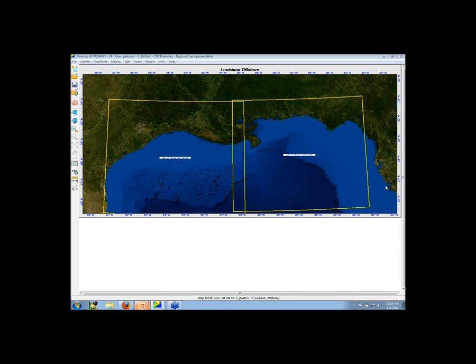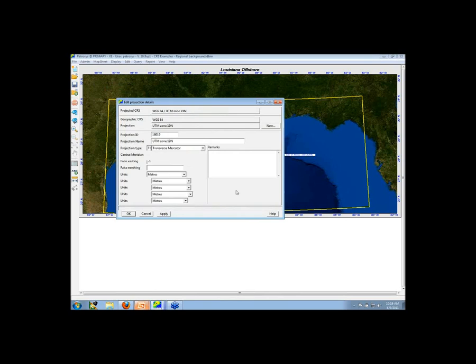So I've got a map here. I'm projecting an image. This is actually the WMS image in WGS 84, and Petrosys is reading that information in the background and is able to reproject it into a new projected CRS. I'm projecting everything here in a more regional type of CRS called the Louisiana Offshore. It's pretty easily controlled in Petrosys. The first thing you do whenever you create a map is define your area of interest as well as the CRS, and we call those things map sheets, and I can just pop open some of the details here. These map sheets, like I said, have the projection system defined, so we're looking at things in a NAD 27 Louisiana Offshore.